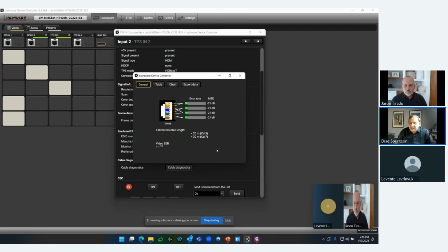It doesn't matter if it exists on a DigiLink Panasonic projector, native HDBaseT connection, NEC, or any other manufacturer native HDBaseT connection. On the Lightware side, that information is present. We're an information company. We're showing you what's going on. So if you take one of our matrices and go straight into an NEC module or straight into a Panasonic projector or any other HDBaseT projector, we can still pull this information, which is telling me very detailed data about the pairs of the connectivity between those two chips.